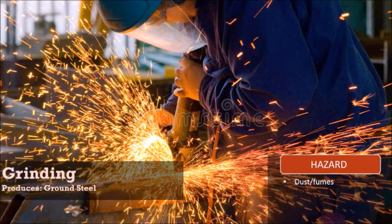Grinding is a subset of cutting, as grinding is a true metal cutting process. Each grain of abrasive functions as a microscopic single-point cutting edge and shears a tiny chip that is analogous to what would conventionally be called a cut chip. After the process, it produces ground steel. The hazards of this process are dusts and fumes.